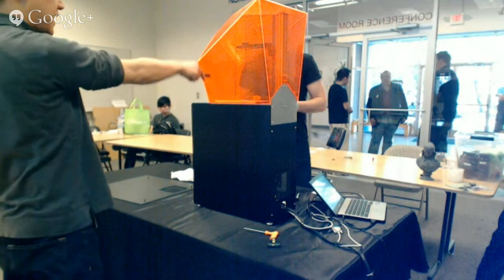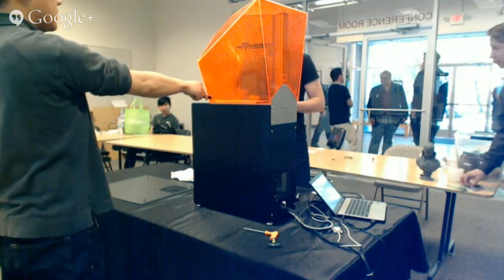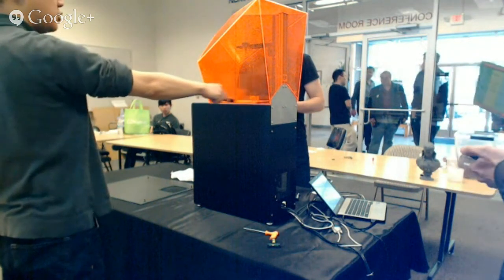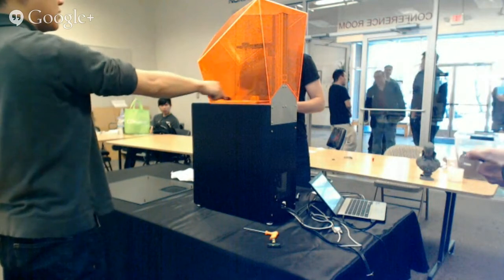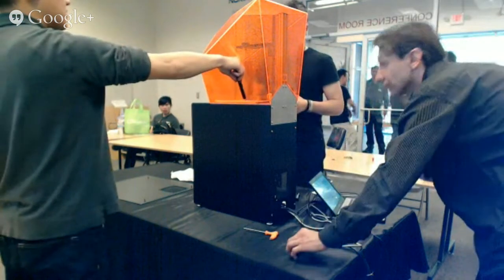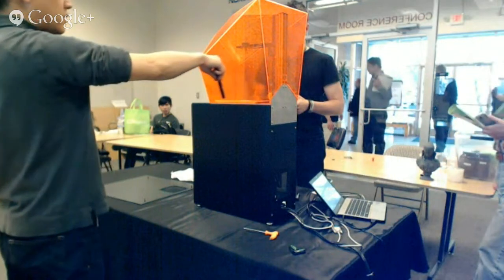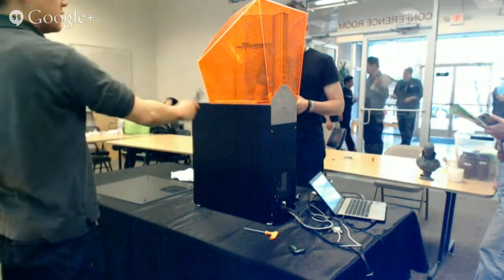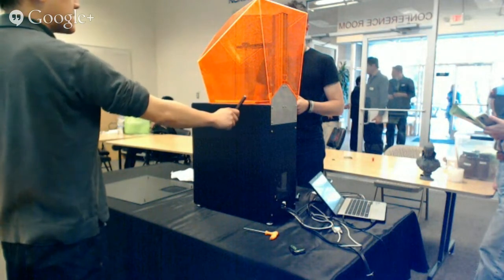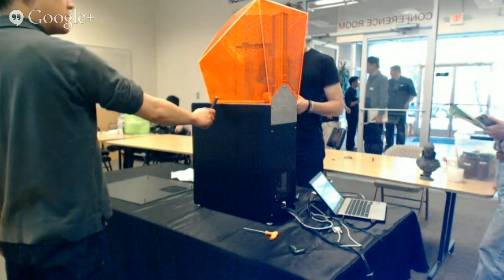You remember that this thing flexed, right? And it's held fixed on this end and it flexes this end. This means that the stress on the part is not uniform across the entire x-axis. There's more stress here because this side doesn't move. At the same time, there's more overall deformation on this side, right? And so there is a big difference between these two. This side is more prone to parts breaking off. Features on this end are more prone to getting a bow in them.